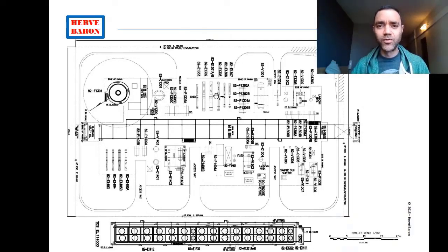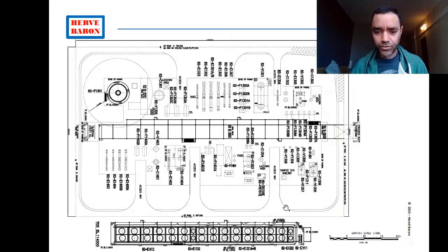In the same way, if we are talking about cooling, we have the cooling water supply and the cooling water return. And probably it will take the same route. So you will return with the piping to the cooling tower system. And with this, you have your total length of pipelines in the discharge of your pump.